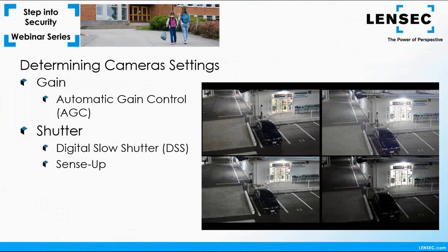The range tends to be from 0 dB, which is off, to 30 dB, which is an extreme setting within the camera. Most cameras would have an AGC, or automatic gain control. This means the camera gain will automatically be controlled by the camera. Surveillance camera manufacturers tend to choose an aggressive gain setting to control an image's appearance in variable lighting conditions.